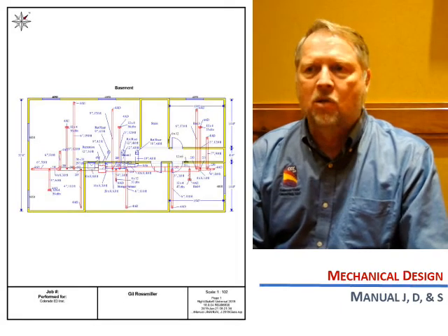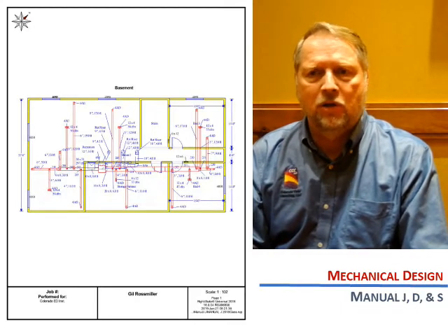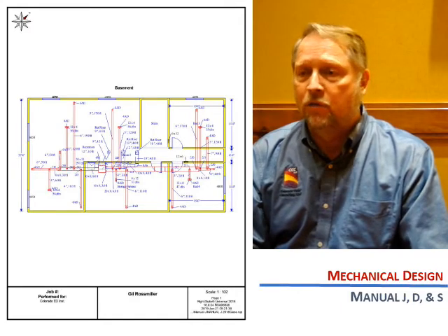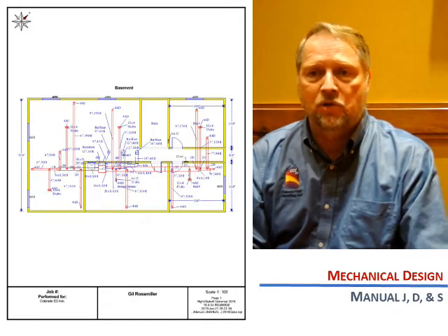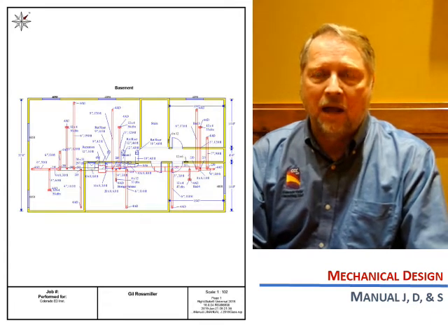Then we should have a duct layout. We should have a duct layout for everybody to review, to build, and to inspect to. We should have the size of all the ductwork, all the fittings, the locations of the registers, and the CFM that we would expect at that location.